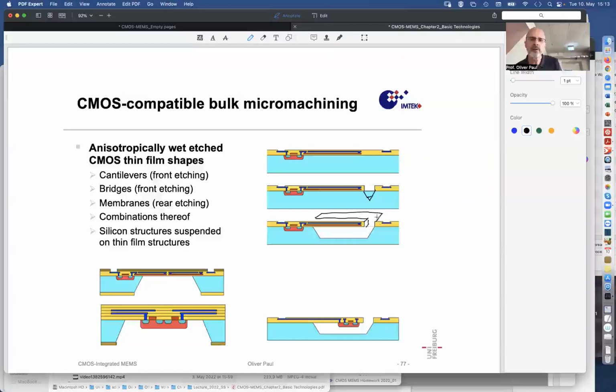So here there is also an edge wall. So here we have now our convex corner. So the etching goes around the corner there, and then under the corner, and then it can slowly progress under the beam to release the whole beam until all the walls are complete, and then it stops and we can only continue in this way.